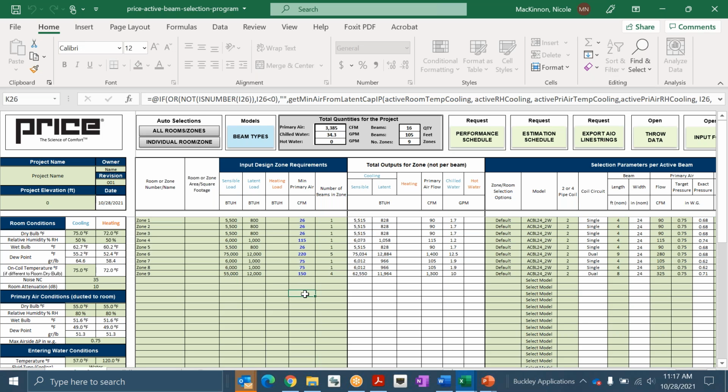Hey, Nathan, got a question here from Matt. Is there any logic behind doing this process before selecting an air handling unit? Yeah, that's a great question. That's absolutely our preference. Whenever possible, we do like to see these done first. So you want to start from the zone level, back that out, see how much airflow you have, and dial in and get those details worked out at the zone level.